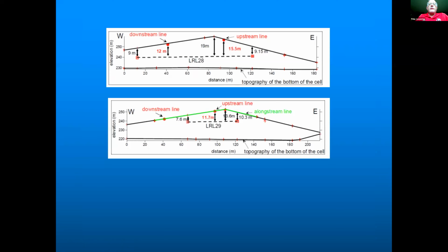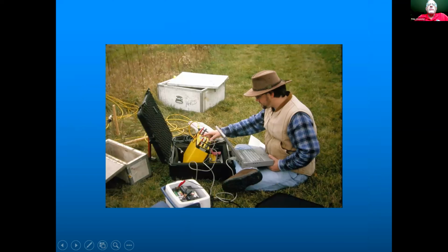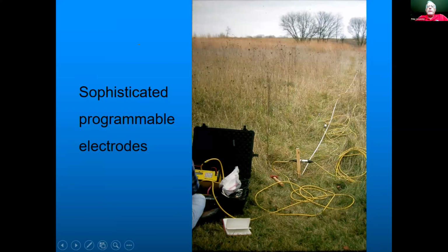So one of the things we did, and Solène did this, she buried electrodes below the cover of the landfill and over time recorded the resistivity changes with a system kind of like shown here, where you have multiple electrodes. You can maybe see them here. They're programmable and they all attach to a computer here, right? Let's see, there's one of my students doing the same kind of work in another site. But that was buried in the landfill.